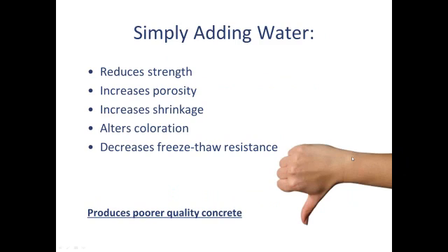So if you just add water to gain your workability, which is probably the only reason why you would do that, adding water, as you know, it reduces strength. Your concrete becomes more porous. There's more voids. There's more channels in it. Those channels allow the water that's in the concrete to escape much faster, leading to increased shrinkage. Those channels and pores are basically sites for future cracking to occur.